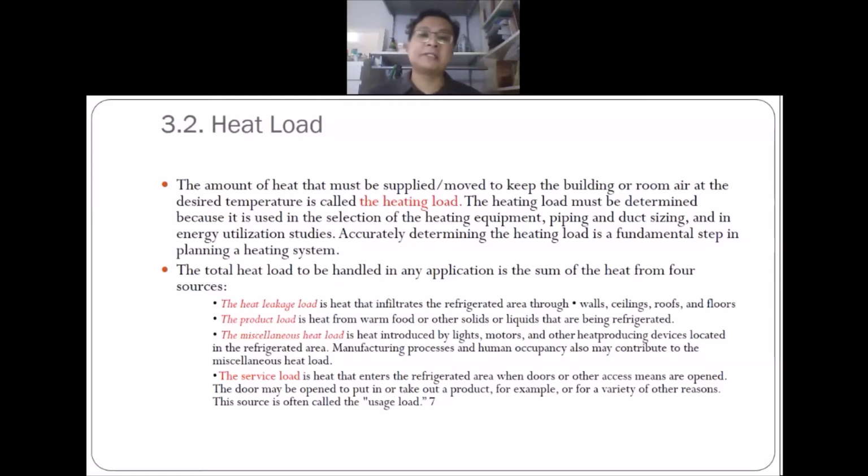So actually, before we start designing refrigeration in a certain building, we should first determine the output, what we want to keep: temperature, pressure, and also the humidity. And then how the room conditions work. Is it for humans? Is it for equipment or something else? So we should design first before we supply the heat load.